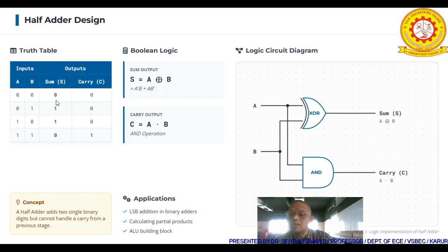Take the sum column. Where 1 is here, because of this 0 we get a bar, and 1 gives b, so it is a sum of products: a bar b. For this other row, where 1 is here, a comes, and since 0 is here, b bar comes. Accordingly, the final derivation is a bar b plus a b bar. So this is the function of the XOR gate.